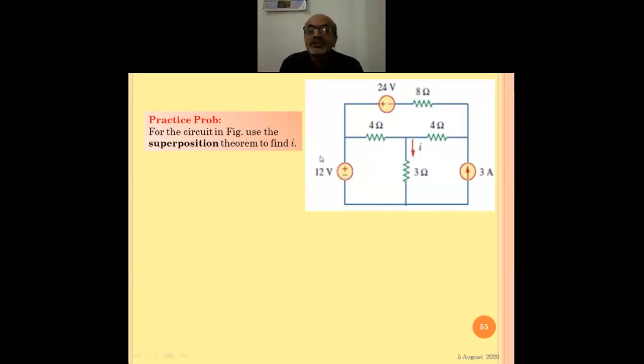So here this I0 dash, let us say that this is the current now only because of this 20 volt. So if now we have to find out this, then again we consider the mesh analysis as I4 and I5. Then again we write the KVL equations for this, and then we take the help of this, that I5, that is nothing but this current, and its current is nothing but the I0 dash. The only thing is that it is opposite in direction, and therefore it will be minus I0 double dash. So if you put that value in the earlier two equations, then we get new two equations, and we solve these two equations to find out I0 double dash, and we find here I0 double dash as minus 3.53 amperes.